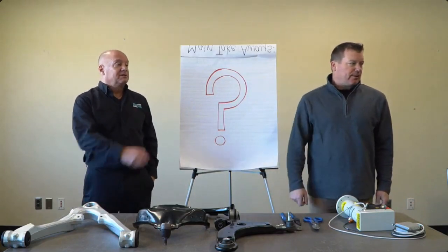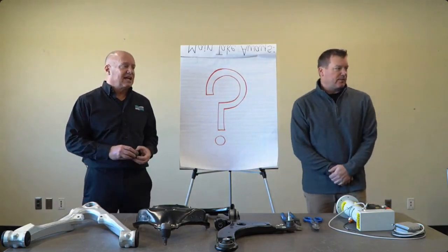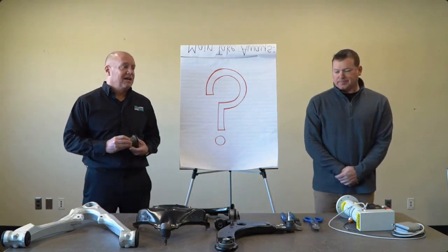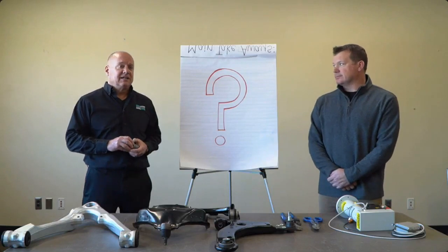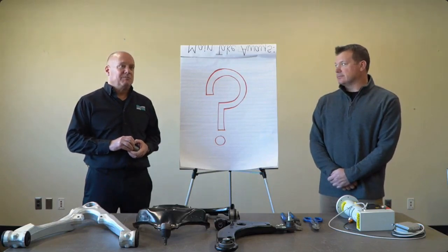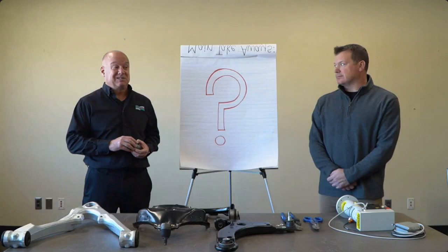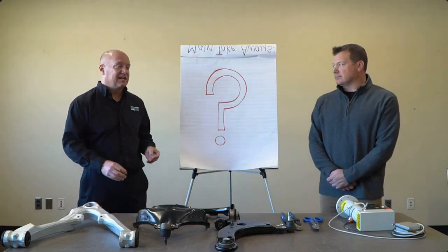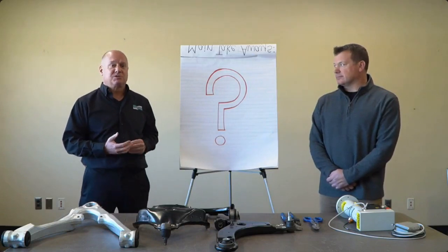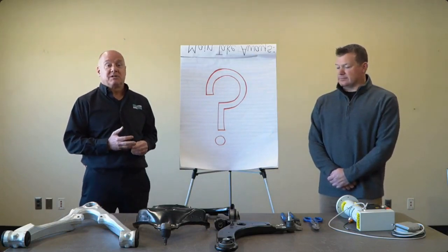Does your press account for deflection in a machine structure? Yes, we have numerous techniques for handling that. One of the simpler ones is if you know the spring rate of your machine structure, say it deflects 10 microns for every 1,000 pounds, the press is smart enough to compensate for that.